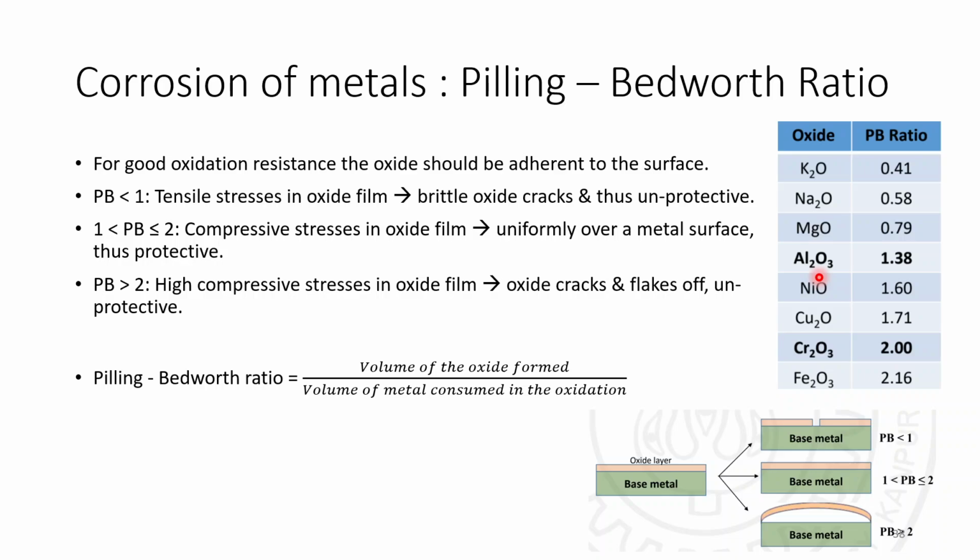Okay, Al2O3 is a ceramic, so ceramic can be used as an abrasive. An abrasive is used when it has higher hardness. These particles are ceramic, so they have high hardness. So when you are using these abrasives, you are using your metals against these ceramic particles. These ceramic particles will form scratches and keep on polishing your material to a higher surface finish.